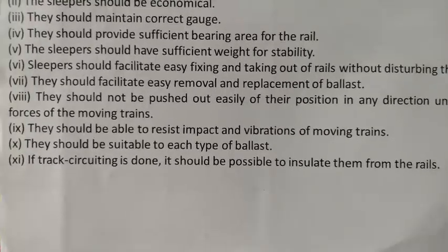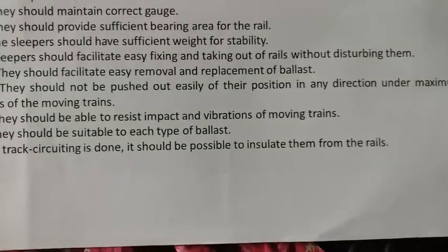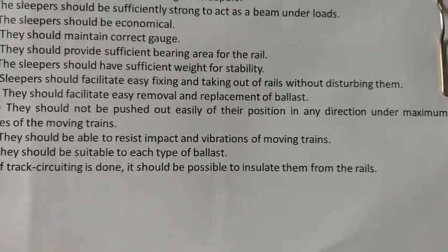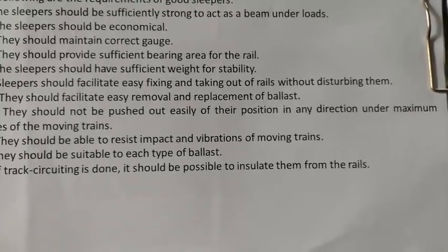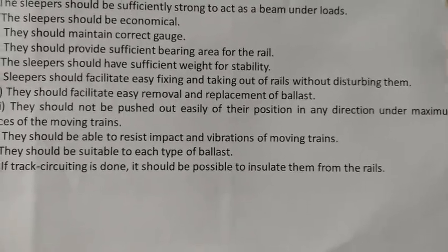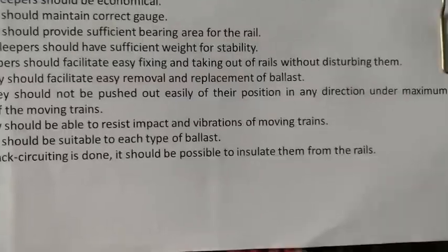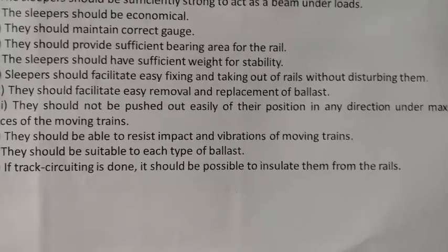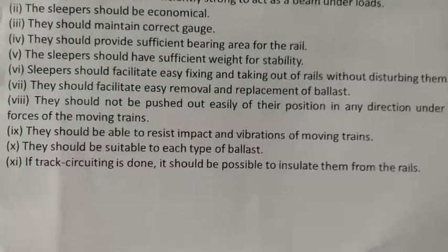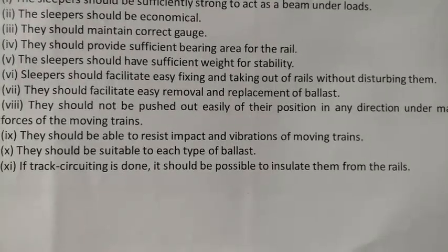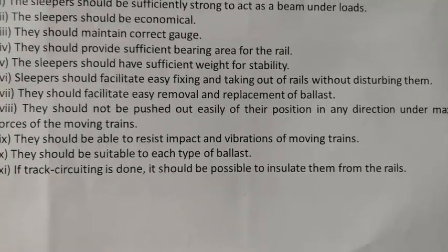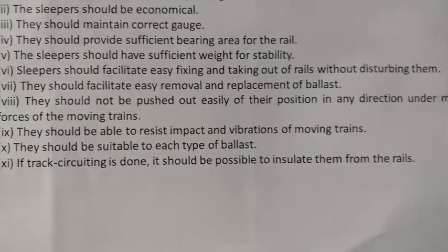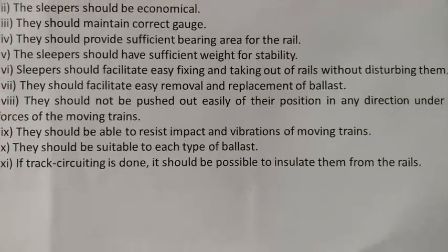They should not be pushed out easily of their position in any direction under maximum forces of the moving trains. This is what I call the lateral and longitudinal rigidity of the sleeper. It should resist the loads acting, both static and dynamic, including the vibratory forces. It should not be moving. It should be rigid in its position. They should be able to resist impact and vibrations of the moving trains. They should be suitable to each type of ballast. If not everything, at least mostly suitable to all types of ballast.